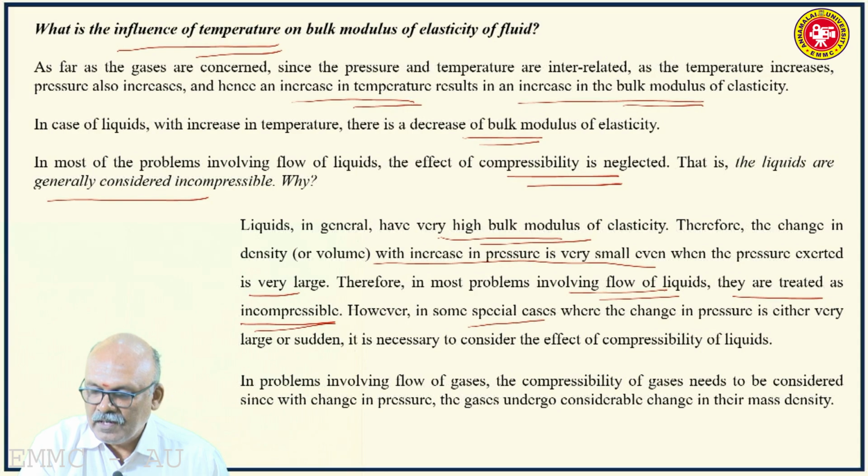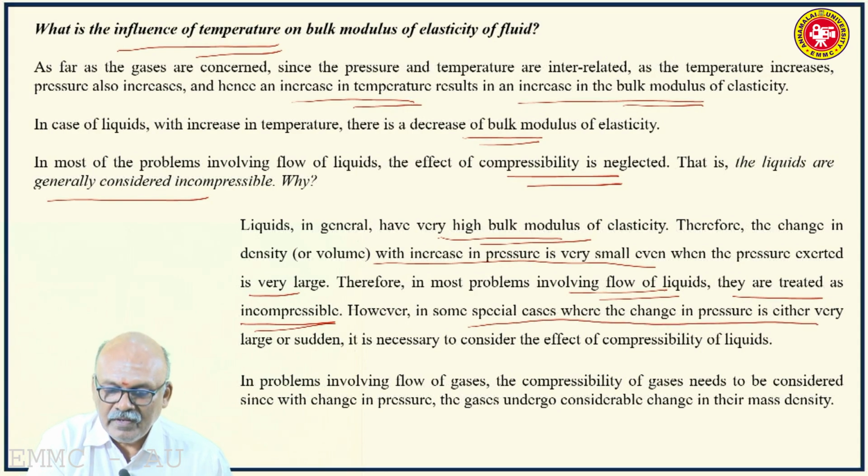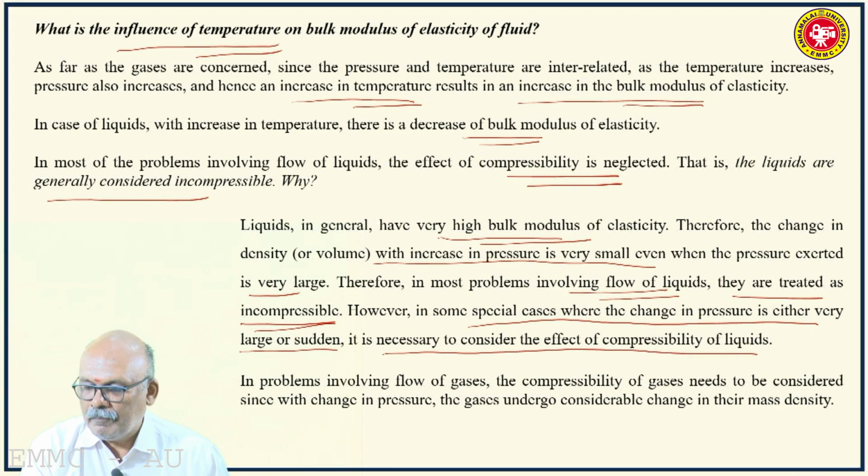However, in some special cases where the change in pressure is either very large or sudden, it is necessary to consider the effect of compressibility. For example, say water hammer in case of pipes. We will discuss water hammer when we talk about pipes. There we have to consider the elasticity of the fluid, that is the liquids. When the change in pressure is either very large or occurring suddenly, then it is necessary to consider the effect of compressibility of liquids.